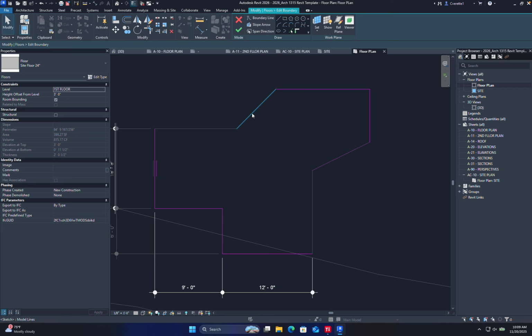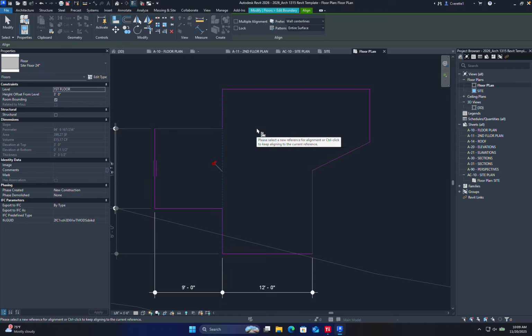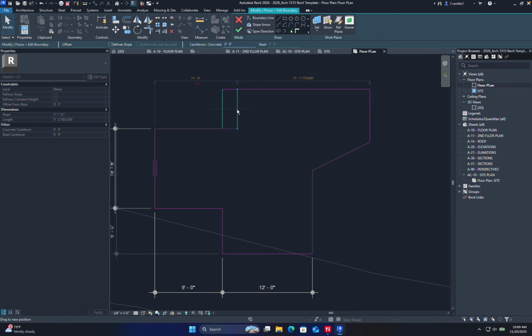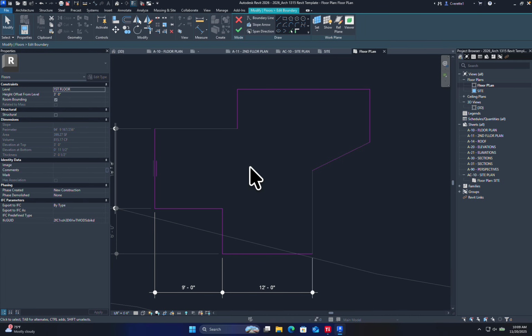The second tool that I really love is the Align tool, and I was thinking of Brandon on this one because he was like, is there any Align tool for Rhinoceros? Yeah, but it sucks, right? In Revit, it is way cooler. I'll type in AL for Align, and it's going to say, hey, what do you want to align to? And I'm going to go, hey, I want to align to this. What do you want to align? This. Awesome. And that is quite the game changer. However, once it's aligned, I can then move it again too, just in case I wanted a difference.